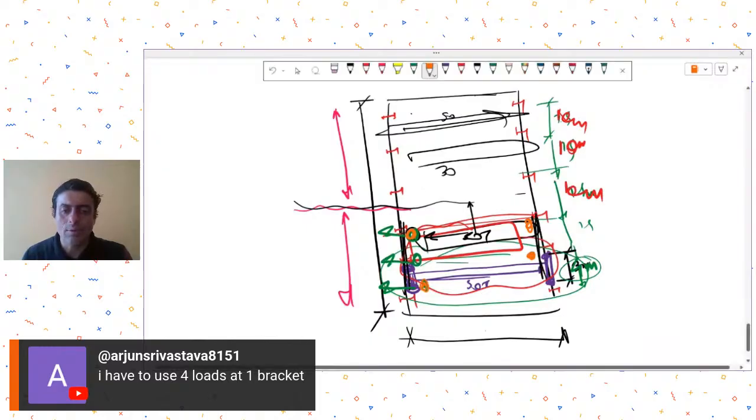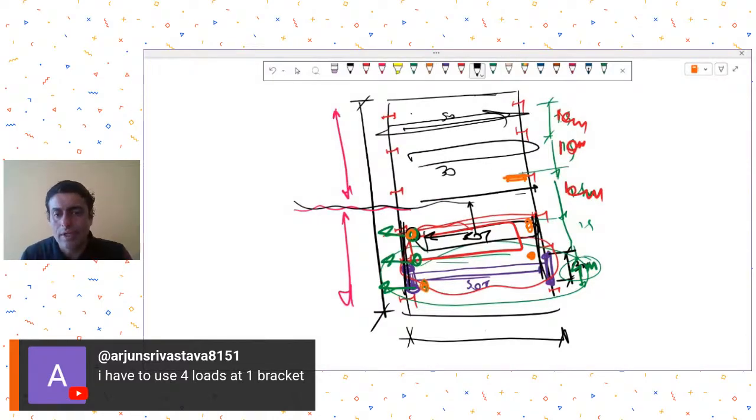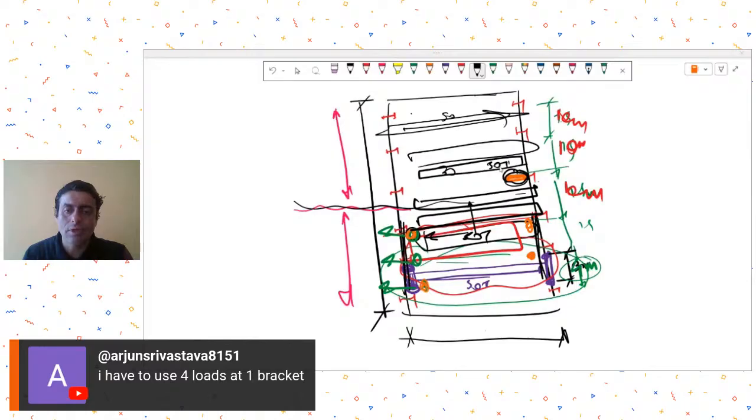First check that out. Then you see for the bracket level. As you are saying, for this bracket, there is a possibility that one 50-ton crane is over here, another 50-ton crane is over here, and right in the next bay there is another 50-ton crane very near. So all loads then get transferred to the bracket. So first you make all the possibilities for the gantry girder, then you check all the possibilities for the crane bracket, and that's how you need to decide.